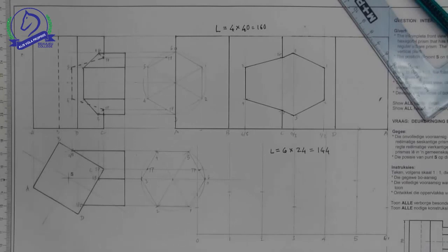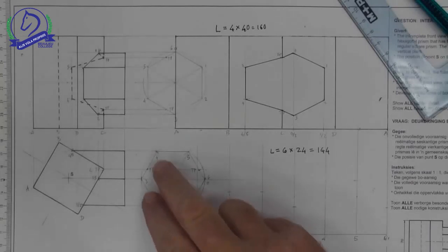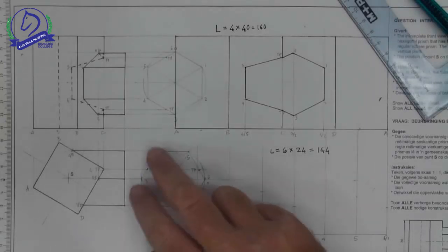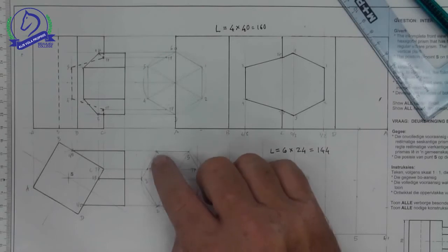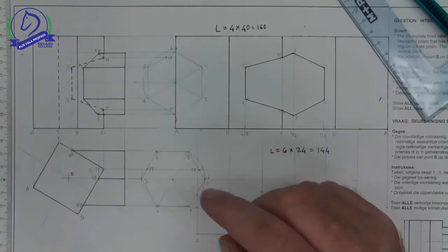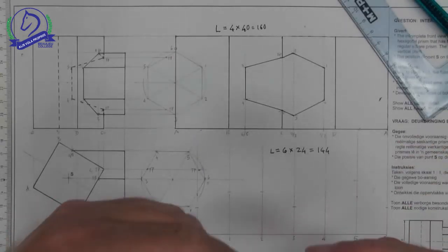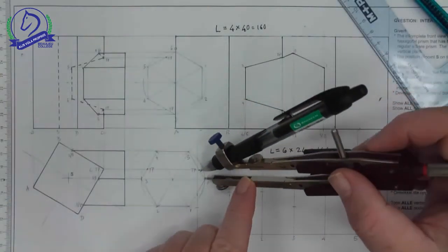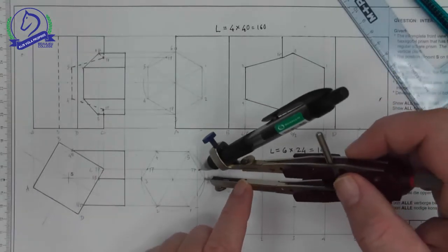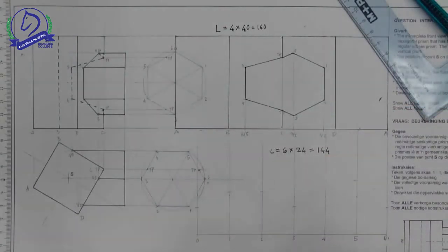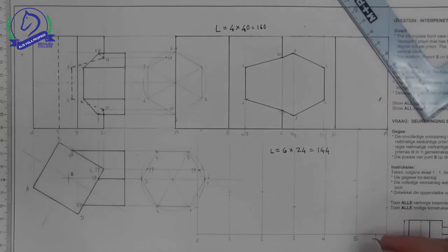The last thing we need to do is find the turning point. So with this we need to go to the auxiliary view. Now generally our auxiliary view has been in the top view here, so we need to get the distance to find where the turning point is on this side between 4 and 3 and 5 and 6. Take one of those measurements. So I'm taking this distance from 0 going towards 5 and mark it off. That's also going to happen at 3 going to 4.